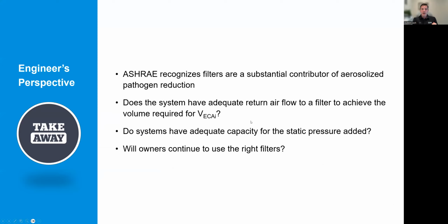So number 1, ASHRAE recognizes filters are a substantial contributor to aerosolized pathogen reduction. I'm going to put on a little bit of a skeptic's hat here, or maybe a balanced view on this. Keep in mind that the particle mix that's used for that MERV rating for 60% removal is a mixture of small, medium, ultra fine, and slightly larger particles. That mix gets you a 60% reduction.